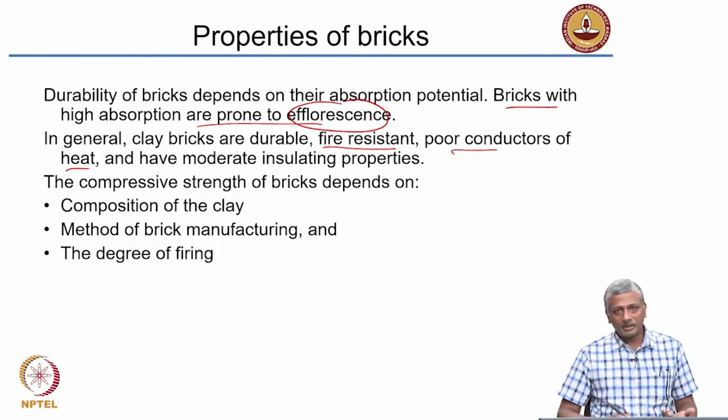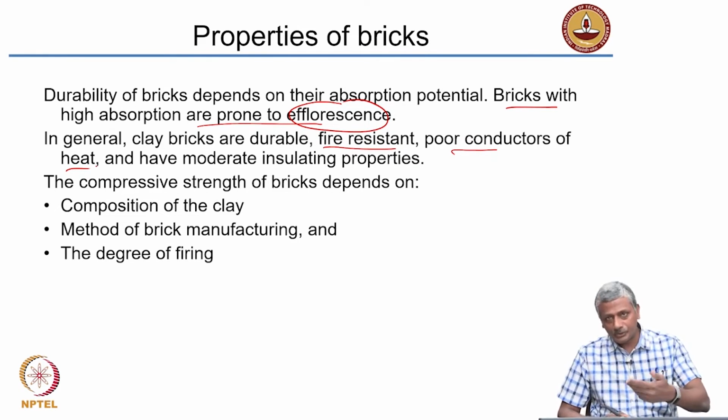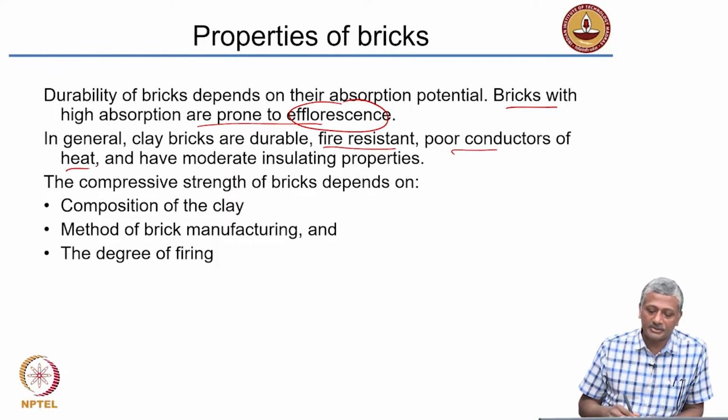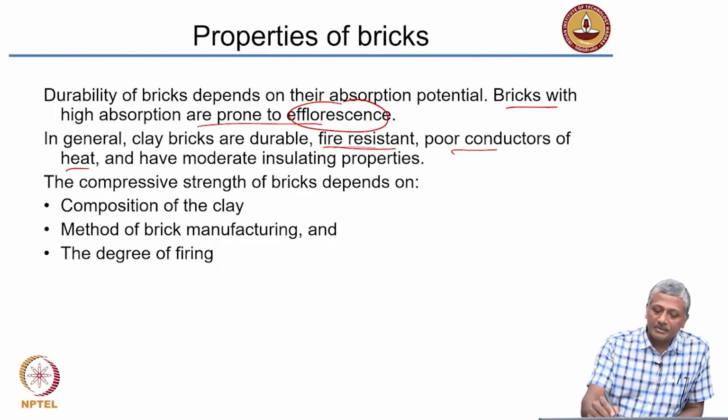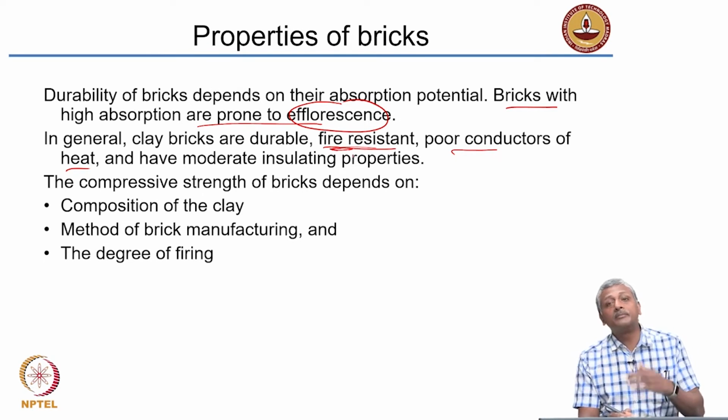And what is improvement in the quality? Essentially it's improvement in the strength and lowering of the water absorption. Okay, I'll describe to you the properties of these bricks in just a few minutes. Of course, as I said, bricks are good insulators or poor conductors of heat, right? And they are also very good against fire. So in most brick masonry structures, fire is not that big of a problem.